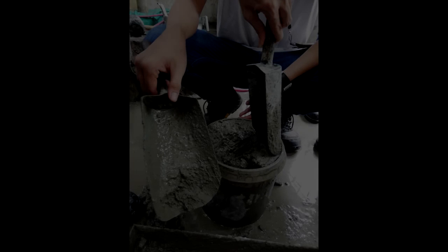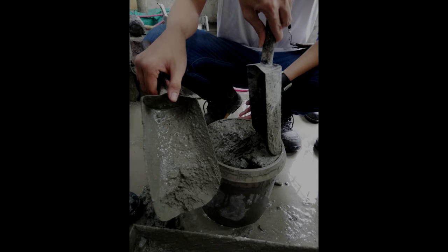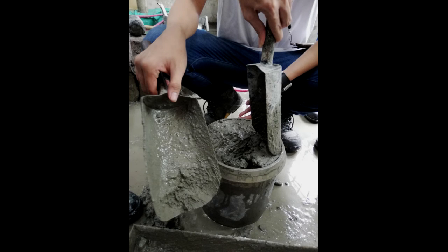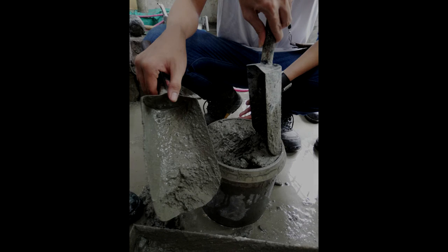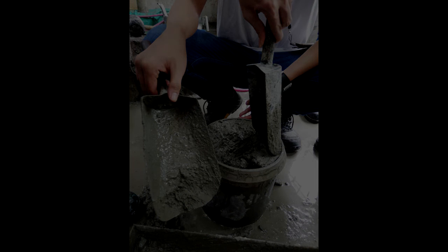To accomplish the experiment, 4 containers or molds were used to hold the concrete mix, 3 of which were in a cylindrical shape while the 4th one was in a rectangular shape. They were first cleaned and then lubricated with oil before placing the concrete. After obtaining and producing the correct proportions of the concrete mix, it was placed in the molds. A tamping rod was used to evenly distribute the concrete in the molds. The concrete mixtures were then placed aside for 24 hours to harden. After that, the concrete specimens were taken for curing.